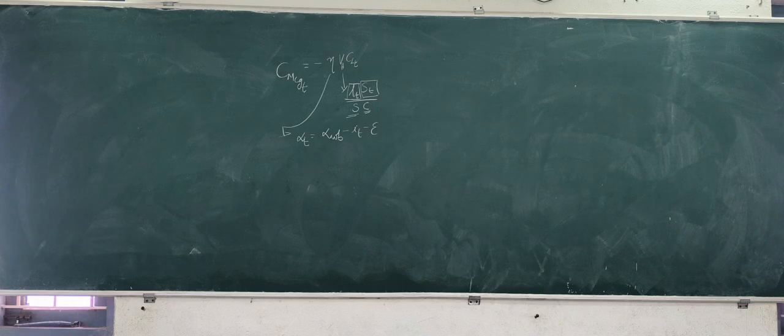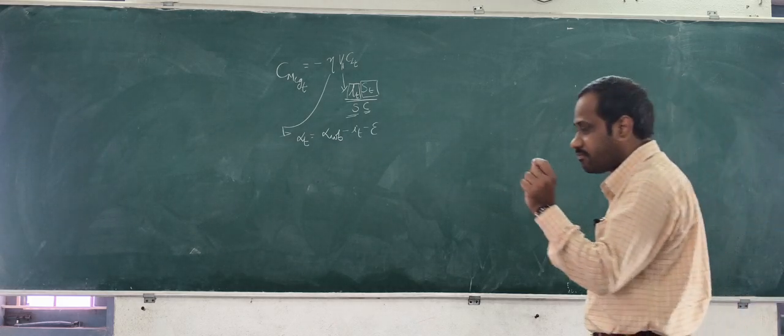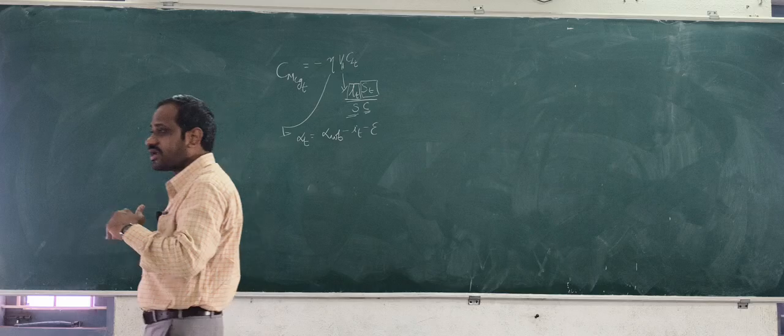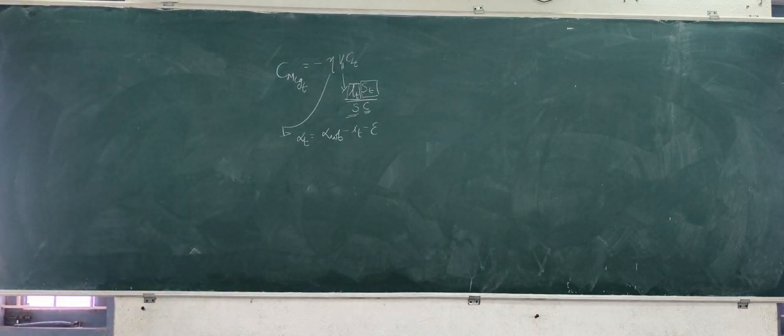In the diagram we have many other parameters. I said the tail setting angle, and we said downwash angle, and we said alpha WB. All of them should also be incorporated into the equation, right? So let us try to incorporate those parameters and write an elaborate equation. Then we'll argue with further details.